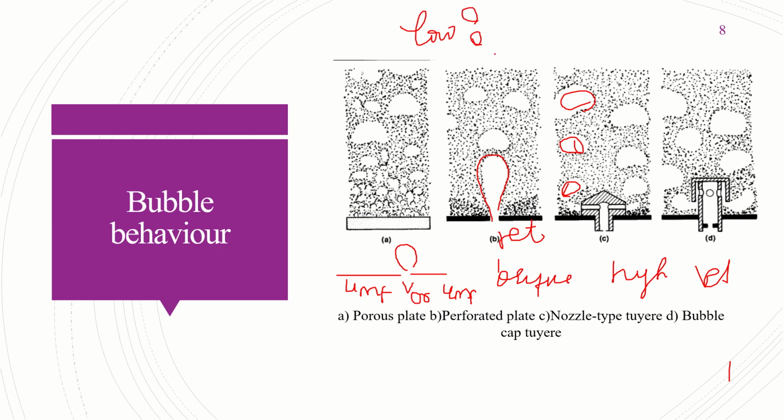And similar to that, there would be a dead zone where particle mixing would not be taking place. So when we increase the gas velocity, the particle size or the orifice size, or decrease the orifice spacing, we can make sure that the dead zone is removed.